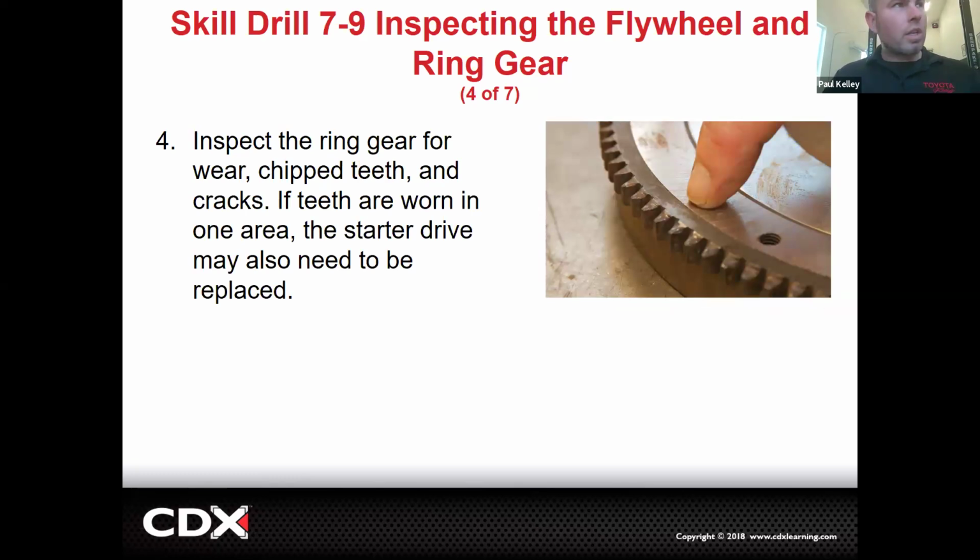Okay, and again, looking at the ring gear, because remember I said I had a friend who overheated it so much this ring gear spun like this. It was just going around and round. And that was the cause of his crank or no crank, depending on how you looked at it, no start. Additionally, we want to look at this because if you have a starter issue and you end up needing to replace this flywheel, it'd be good to replace it now and figure out the starter issue.